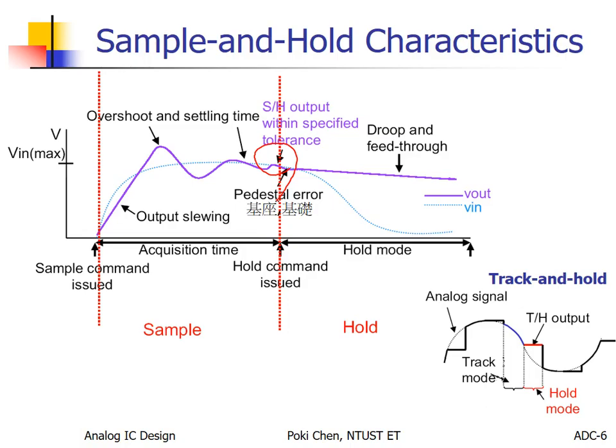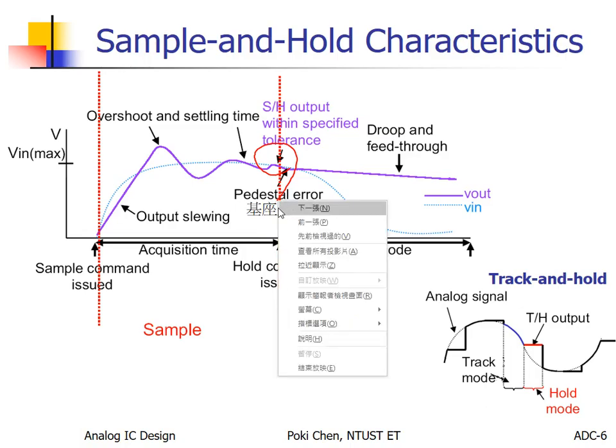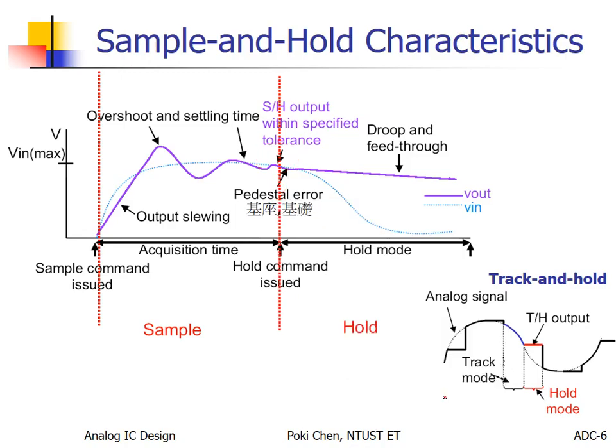But after you turn off the switch, according to charge injection and clock feedthrough, if you zoom it in, you can see that is the original one. Finally, V out and V in are the same. But after turning off, you will usually have something like this, a step.